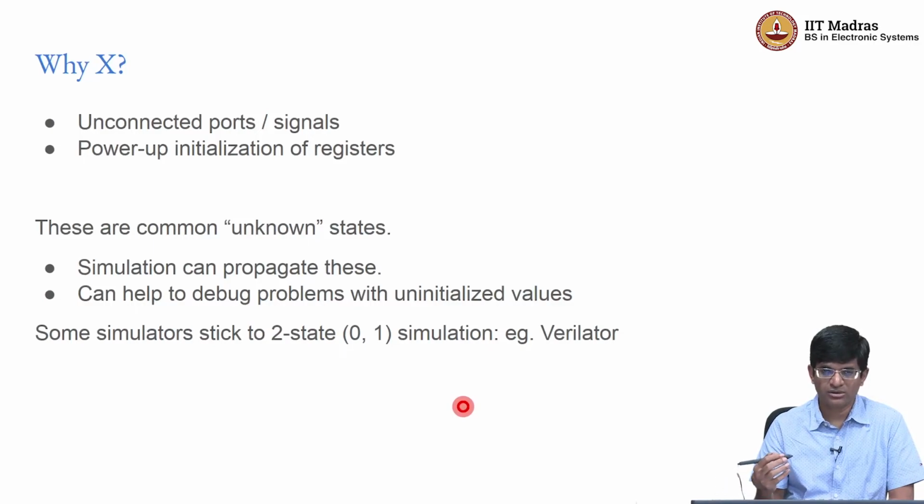Now, having said all of that, it is in some sense a limited kind of functionality. We ideally should not need to model debugging based on whether or not we are able to propagate X values, because we should be ensuring that every part of our circuit is initialized properly to start with. And because of that, there are some well-known simulators that do not follow the full 0, 1, x, z kind of 4-valued logic and instead just stick to 2-state simulation.